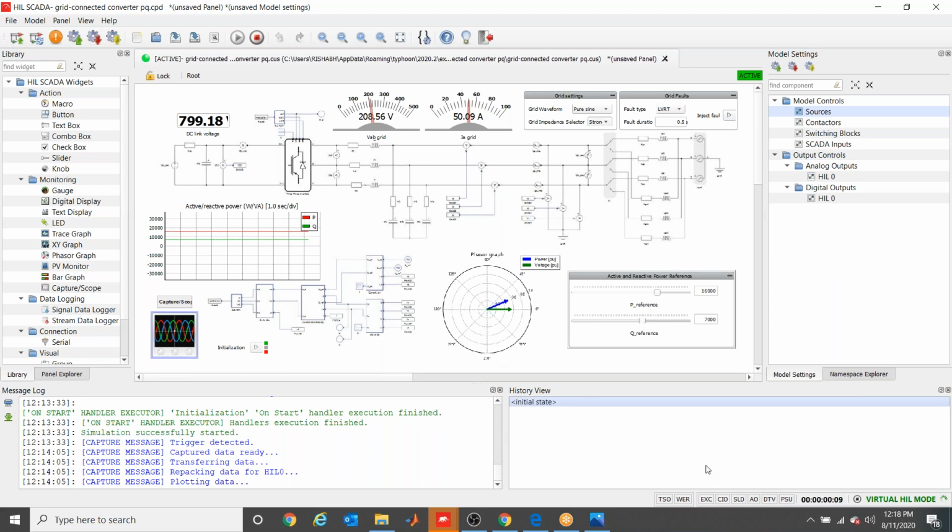So it will not be using my computer CPU. It will be using the CPU inbuilt in the HIL. No, you're not understanding the basic thing. See, yes, in Typhoon HIL there are two types of processor. One is your FPGA, which has some number of cores; if it is a 6 series, then it will have 6 cores of FPGA, and it will have two CPU processors also. One is ARM and another one is MicroBlaze. Of the ARM, one is user defined and another one is system defined.